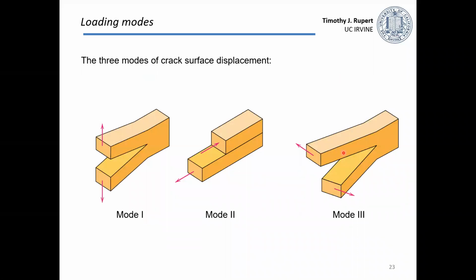I do want to mention there's technically different ways that we can open these cracks inside of our material. What we were showing before was there being a center crack and we're pulling on the sample in the vertical direction. This is what's called mode 1 opening of cracks. You can also think about applying the stress in different directions. You could have it be applied in a shear direction and open the crack as well, or in a tearing type of direction. And these are just called mode 2 and mode 3, respectively.